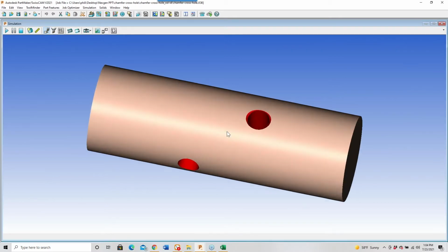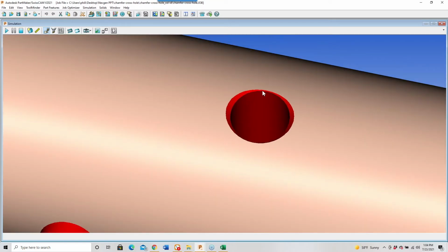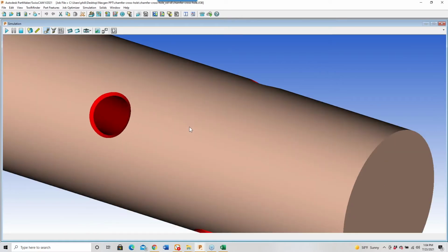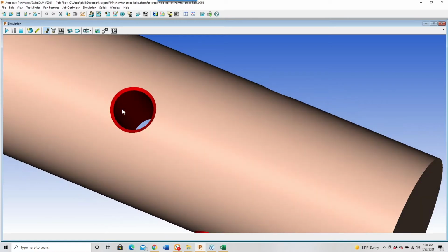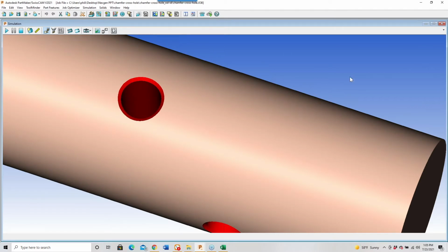And the drilled holes that are just using a standard spot face, the result is a thick and thin chamfer. But using this technique where we use the C-axis to keep the tool coincident with the edge of the part, we can get an even chamfer on the OD of the part, even without having the solid model.